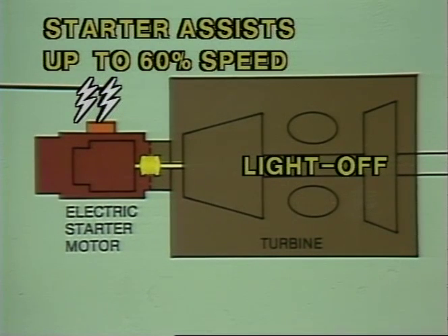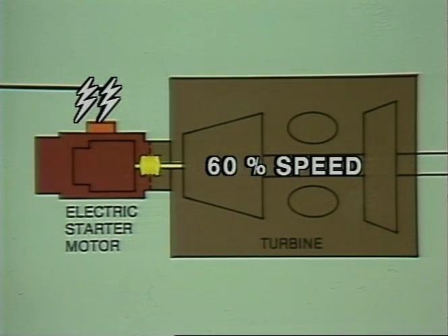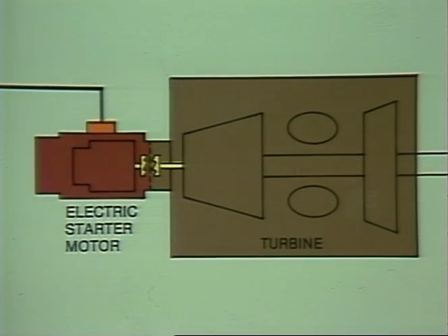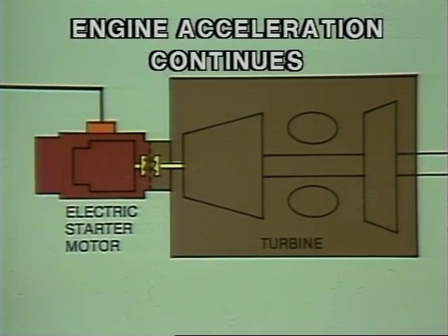Upon reaching 60% speed, the soft start and main contactors are de-energized, which causes the jaw to retract and the motor to coast to a stop. The engine will now accelerate on its own power up to rated speed.